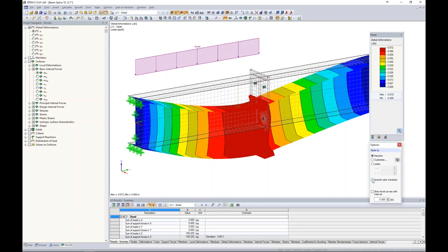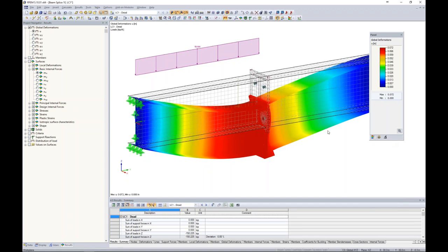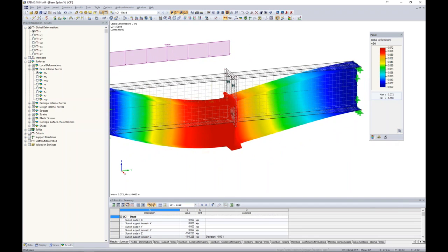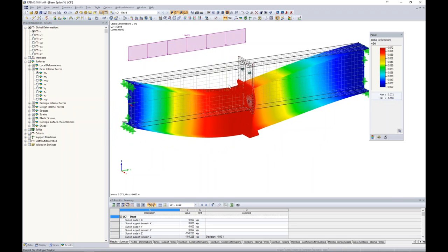So to me, I think the most important thing to automatically take a look at is deflections. Deflections are really going to show us if we've correctly defined our contact solids, maybe our FE mesh, and if it looks to about what we would approximate. So it's kind of a little bit difficult here to see our deformations and what's going on.